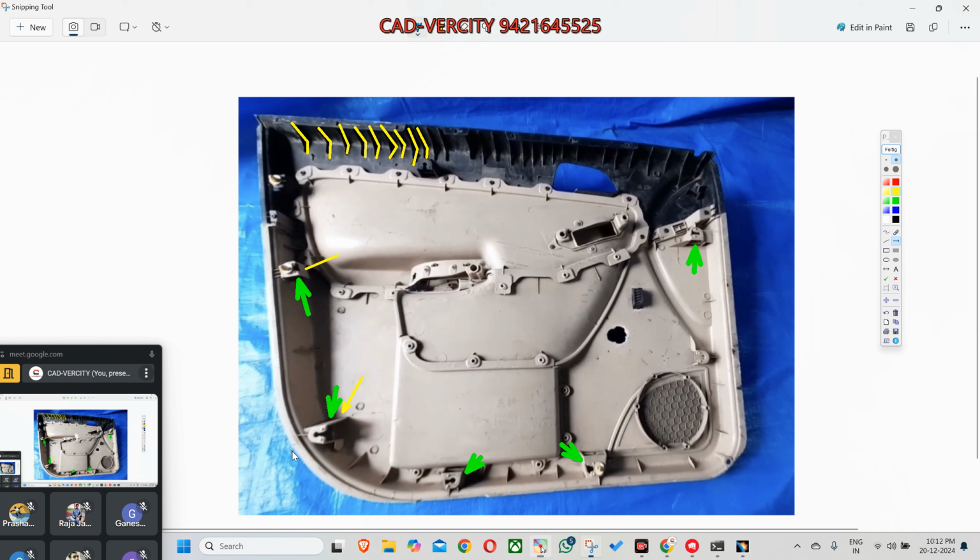So what should be the travel length? Consider this as an undercut. Let's say x mm. So what should be the travel length? Yes, Ganesh. X plus Y. Yeah, X plus 5 to 10 mm. This will be the x and this will be 5 to 10 mm. So this will be the travel length. So in this area there should be nothing.